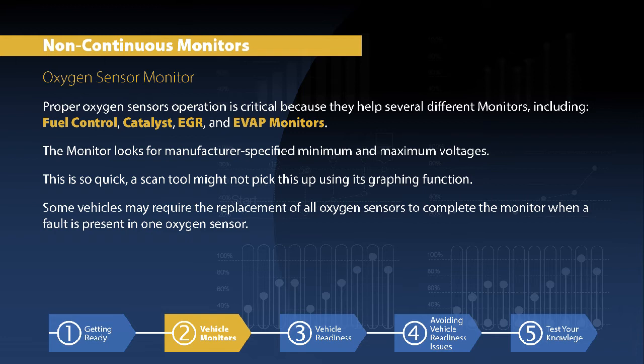A lot of factors can affect the relative richness or leanness of the fuel mixture, including air temperature, engine coolant temperature, barometric pressure, throttle position, airflow, and engine load. There are other sensors to monitor these factors, but the O2 sensor is the master monitor for what's happening with the fuel mixture. Consequently, any problems with the O2 sensor can indicate problems with the entire fuel system.